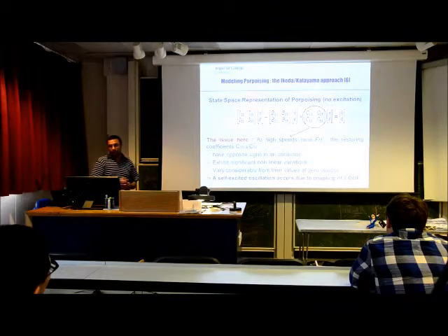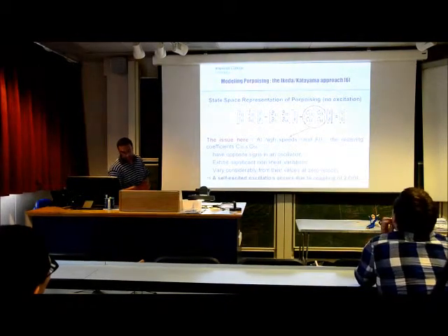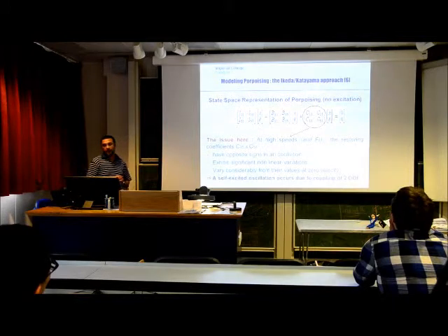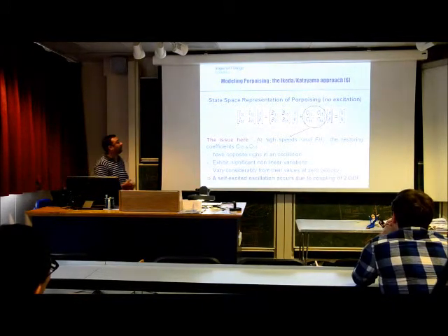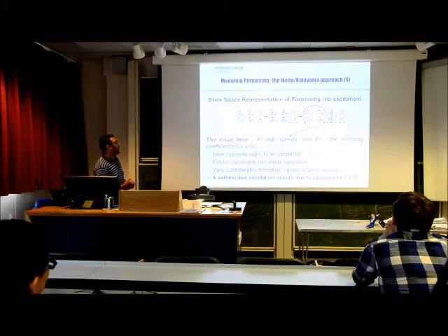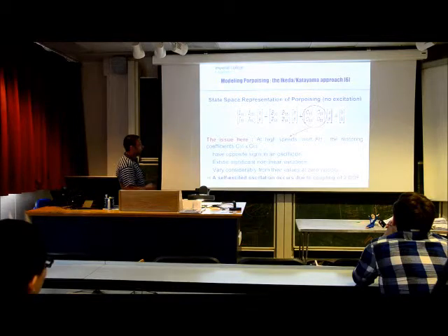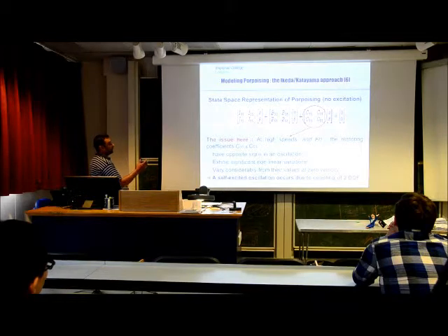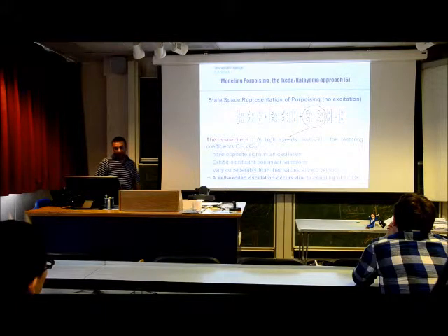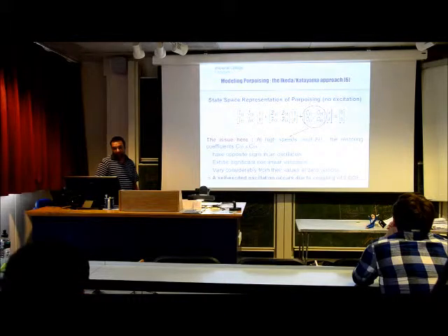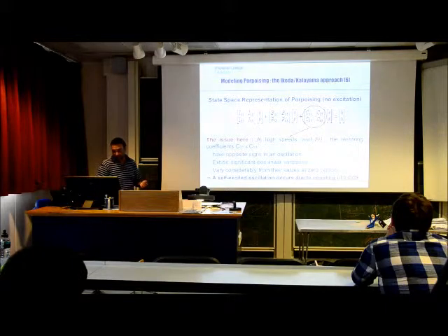So porpoising, the equations of motion, the state space system, has been described by some research work. But the problem is, as the speed rises, which will be the case for us when we take off, there's a lot of non-linearity going on with the restoring coefficients, inertia coefficients in one of the terms. Namely, the porpoising is initiated when two of those coefficients get opposite signs.